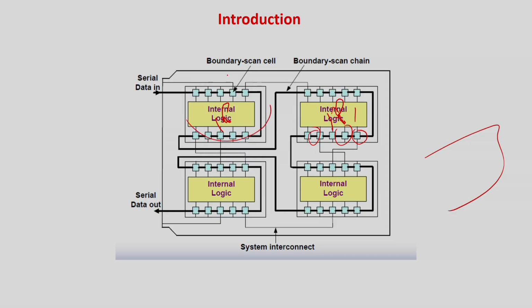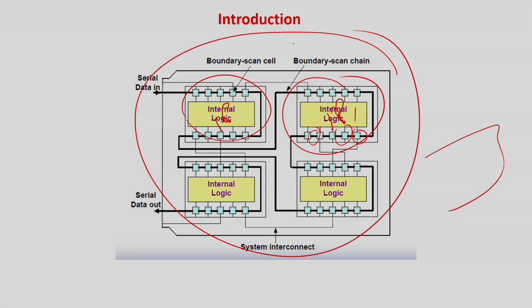Again repeating, this is the story with any embedded system core based design, because the cores are somewhat chips in themselves, but they are not at the level of external devices which can be put on a breadboard or a PCB. Rather this is a single silicon die, and you are putting all these at the fabrication level, so that the delays between these interconnects are much lower and you can have a higher frequency of operation for the entire embedded system hardware.